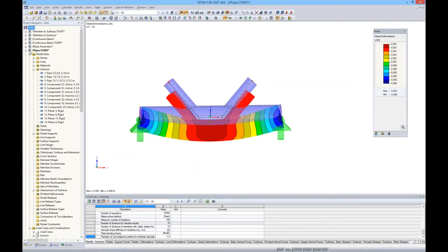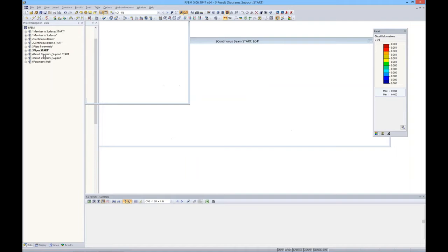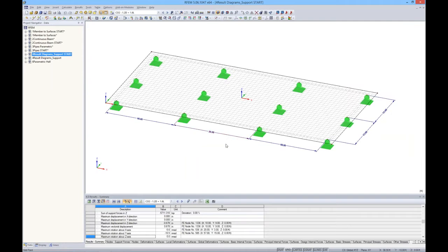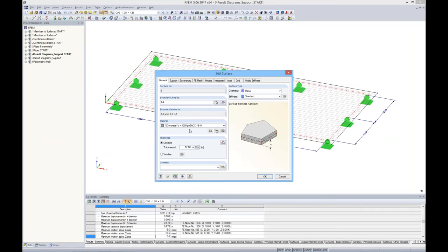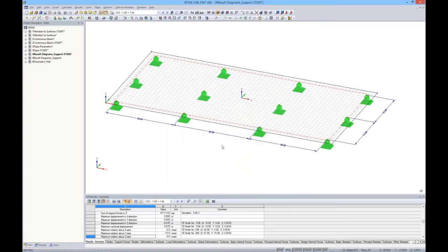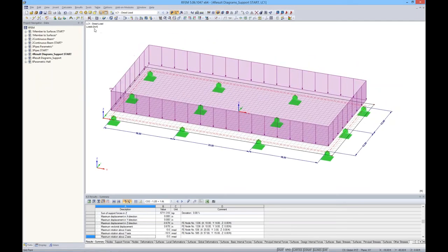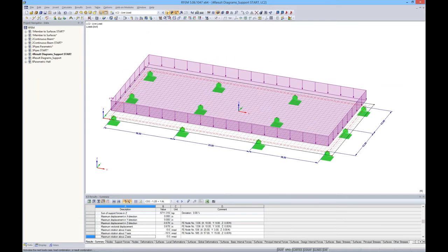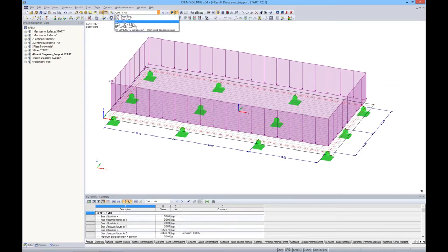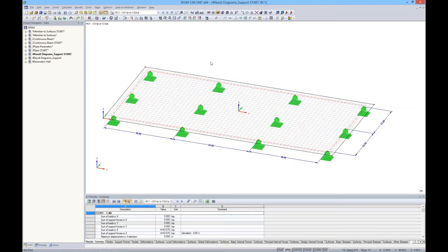Okay, so moving on to our next example is just a typical foundation. It's a concrete foundation. If I go ahead and double click on it, I have defined it as 4,000 PSI concrete. It's 12 inches thick, maybe a foundation or an elevated slab, something of the sort. I also have applied a few loads here. Just your typical dead load in KSF 1.5, maybe a live load of 0.75. And then I also have a couple load combinations here according to ASCE 7. Then I also have the result combination for the envelope solution.